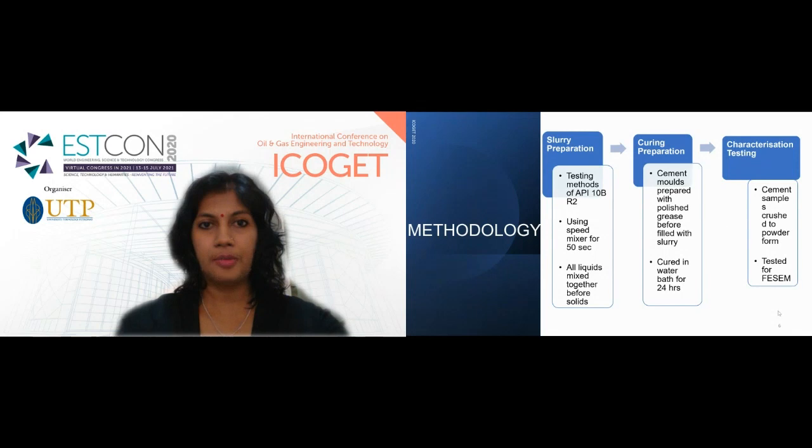First is the slurry preparation, where the slurry is prepared according to the testing methods of API 10B-2. A speed mixer has been used with different ranges of speed for 50 seconds to mix the solids and liquids together. All liquids are mixed before solids are added to the geopolymer system.